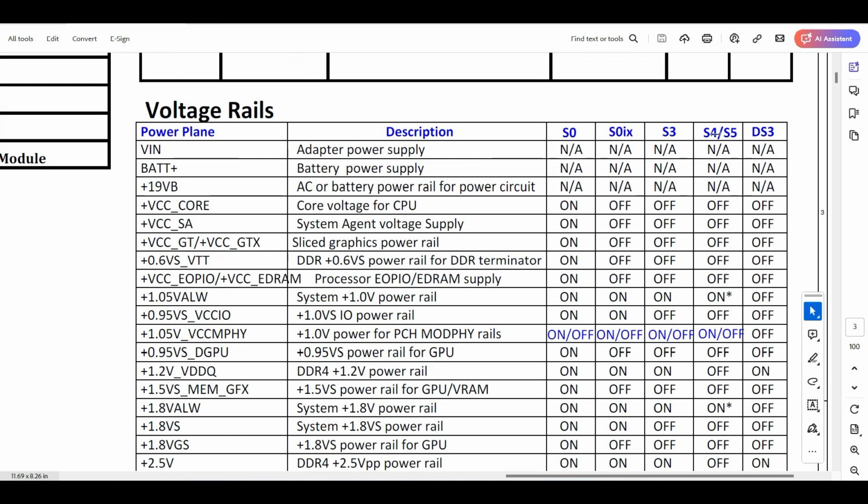The second thing is the stages you need to understand. In all motherboards there are multiple sections, stages. One is the S5 stage, S3 stage, then S0 stage. Only these three you have to keep in your mind. Don't give more concentration than this. Why, I'll tell you later. These are the basic things in any laptop. If you don't give concentration on this, you can't repair older laptops. That's what I'm telling you.